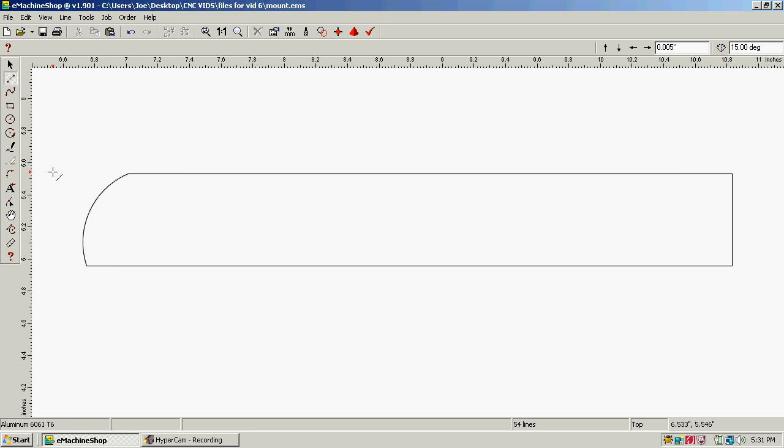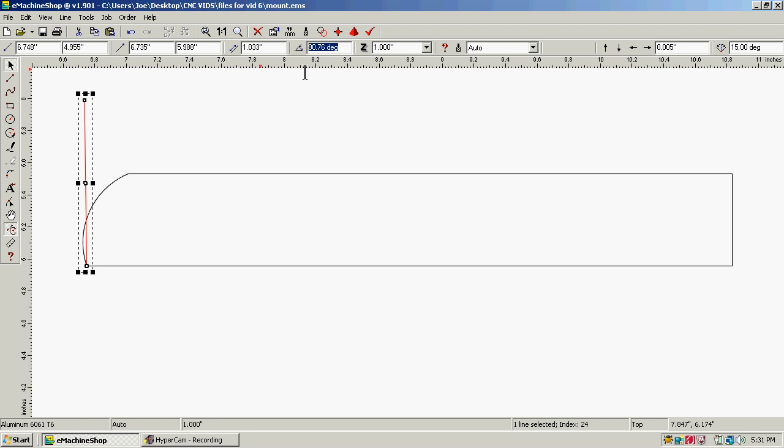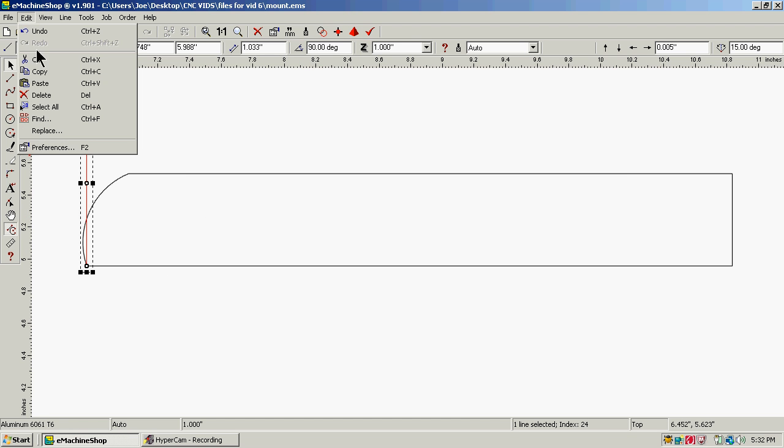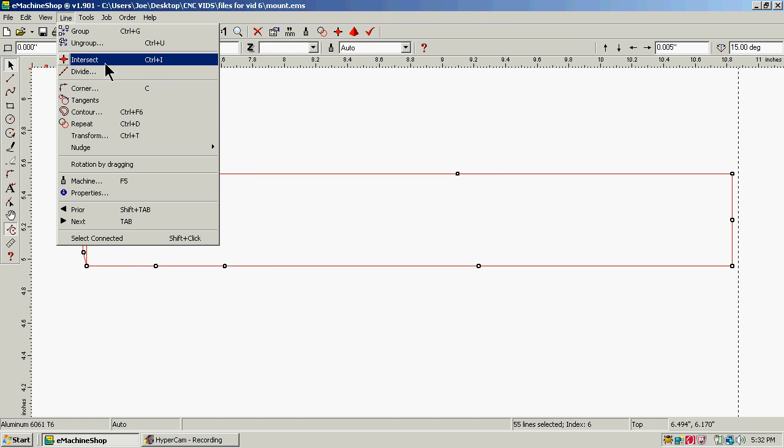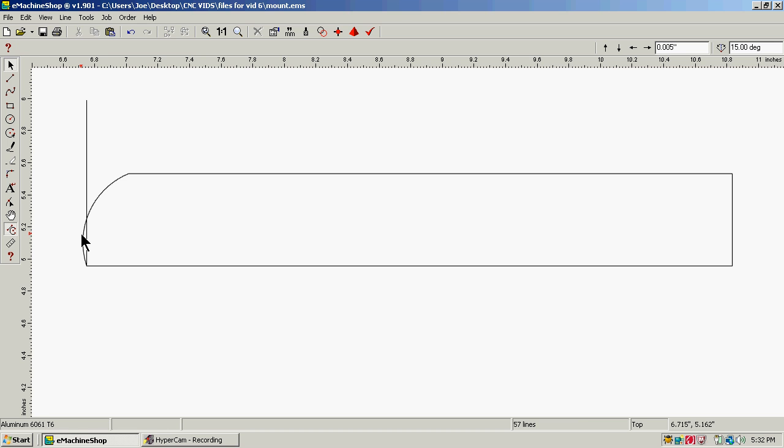Oh, sorry, I'll show you something here. I can hit snap again, turn snap back on, draw a line from the corner of it up, come to the top until it is 90 degrees, hit enter, select it all again, intersect the lines again, take this section off this time, and then that's the arc you were talking about. I hope that's the arc you were talking about.